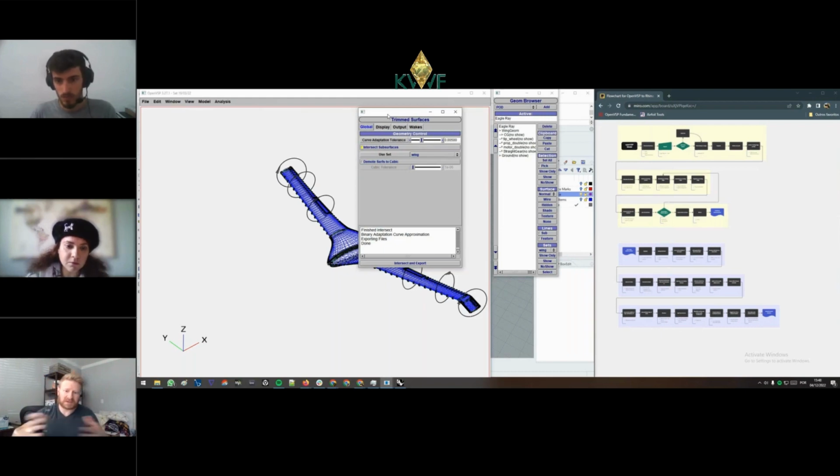So that's how it's rebuilding everything. It's defeaturing a little bit into a lower order Bezier curve, so it's easier for it to loft through. So you won't have 100, 200 points going through that. And even though that's really close, on average, you might get that 0.3 millimeter deviation. The thing that bothers me is where is that deviation?